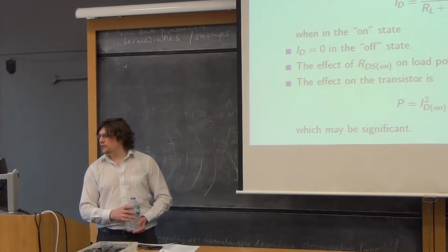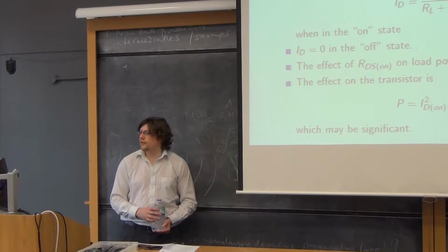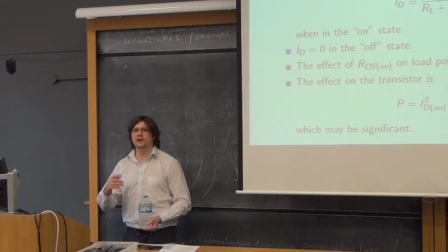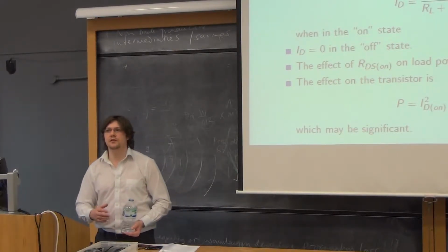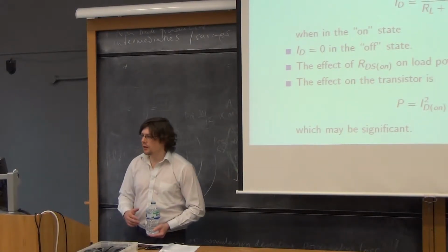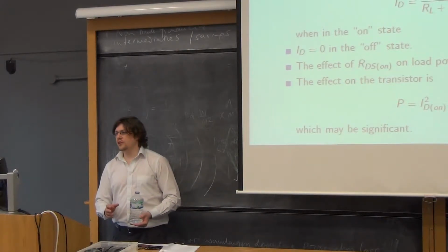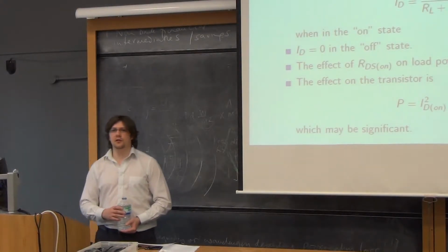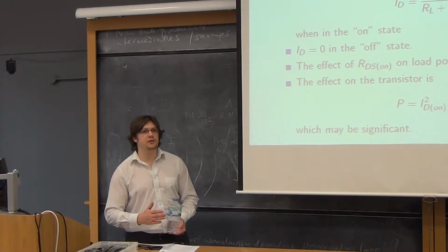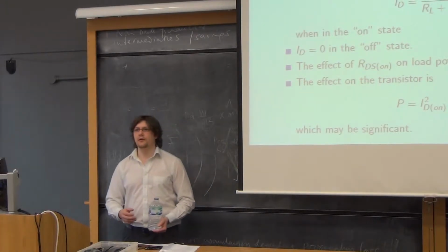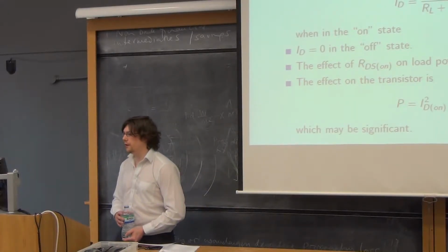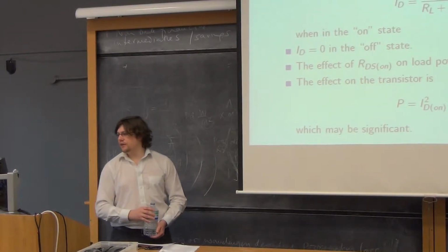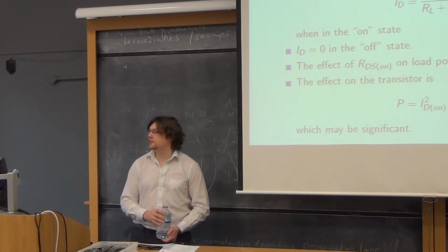So from lecture 10, the MOSFET behaves like a resistance when it's on. That's to say, I said there would be some RDS on, and we can just assume that between the drain and the source, which is equivalent to the emitter and the collector, there would be some on-state resistance. And the manufacturer will specify RDS on for whatever particular current that you're interested in, or they may just give you one value if it's not varying very much with drain current. But we can work out what the drain current is. It will be Vs divided by RL plus RDS on.